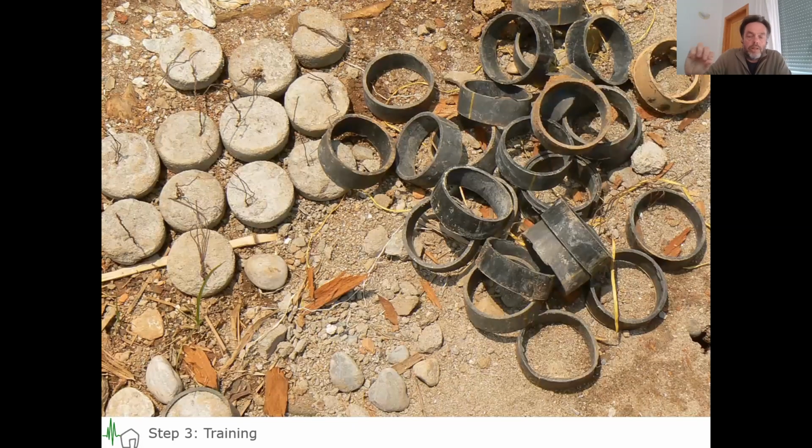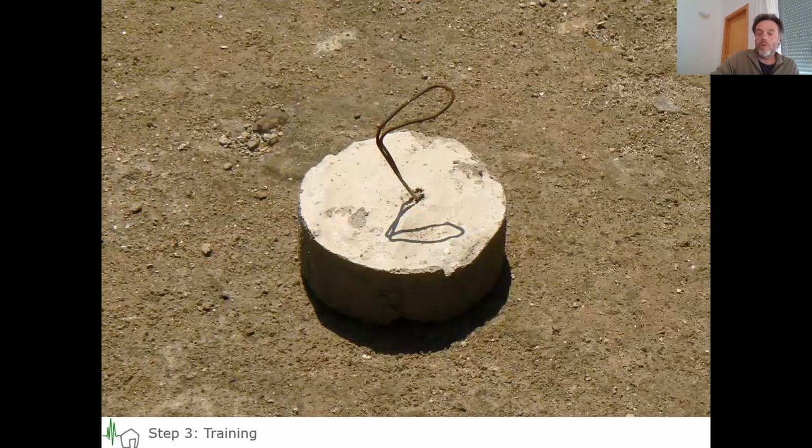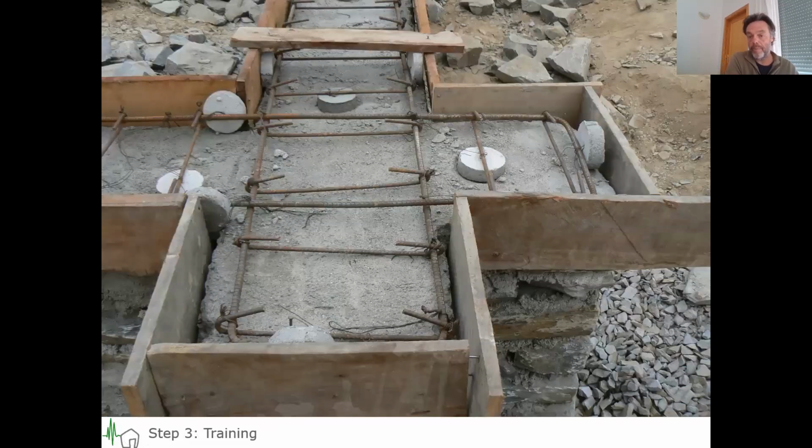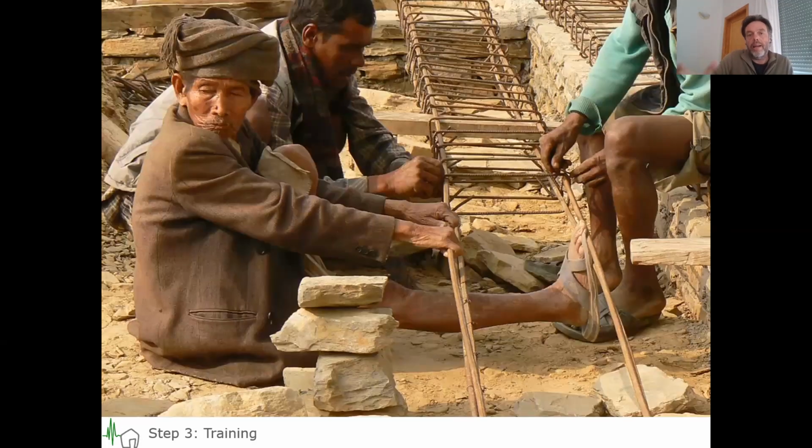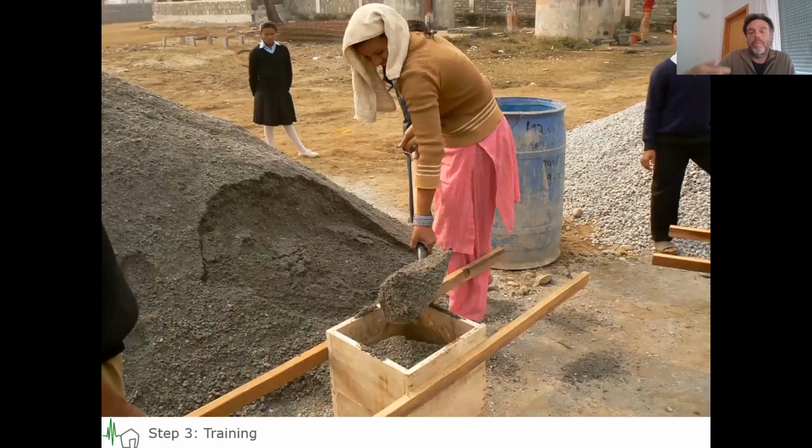So what we did, as a trick, is we introduced spacers. You can do this with a pole of bamboo or with a PVC pipe. You fill it up with some cement and a little bit of steel wire inside, and this is your spacer. These spacers are placed under the reinforcement, but also next to the reinforcement, so that between your formwork there's always enough distance, let's say 3 centimeters, between your steel and the outside of your beam. And we teach them about proper bending of steel and how to apply all these stirrups and how to bend them in the right position.